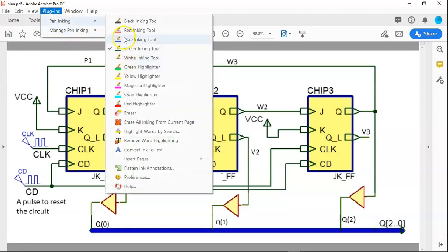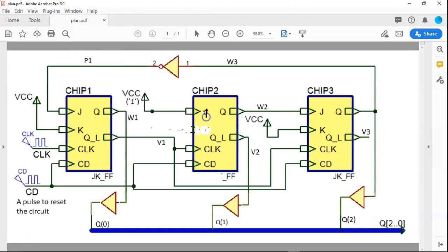So now you can mark that like that. So this is going to be the T. Okay, and this is the T flip-flop. All right, so for example, this is the signal W, and this is connected to nowhere but has a name, B3, and so on, right? So you give every signal a name, okay? That's one way to go before starting the development. So now you only have to get the components and the signals to organize the top entity, which is going to be this design, right?